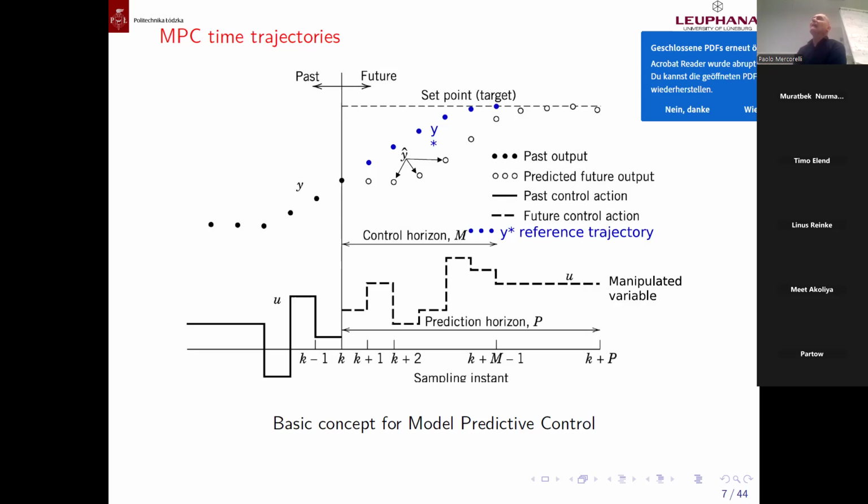The idea is to calculate this manipulated value for the future, even though I will apply just the value which I will obtain at the step k, and each time I will recalculate again, considering a receding horizon. Because today I am here, I will predict, I have this goal, this blue line in the sense of points, or sampled line.